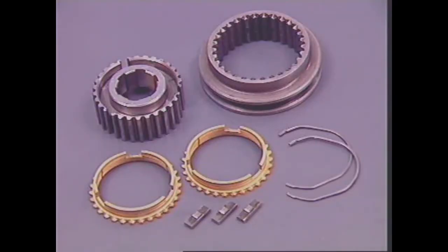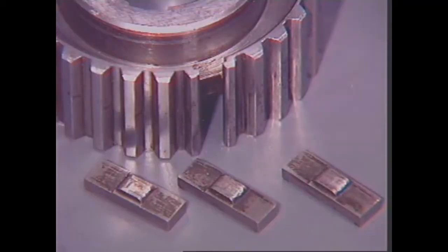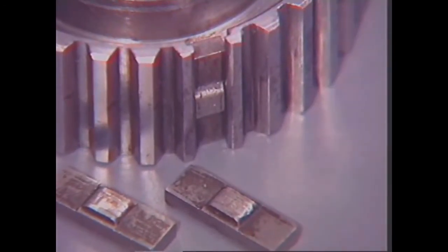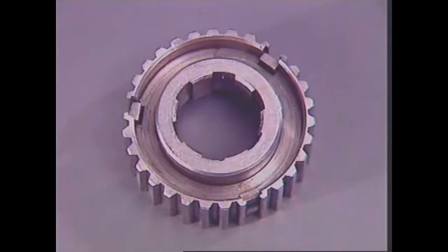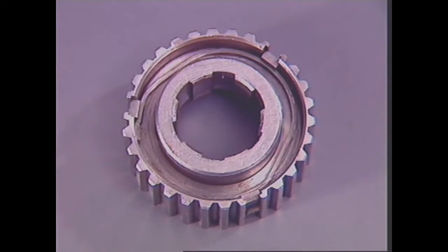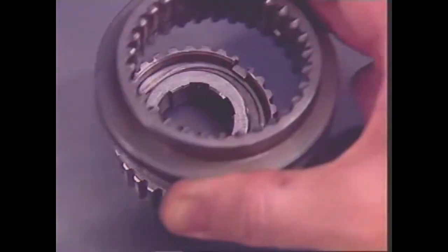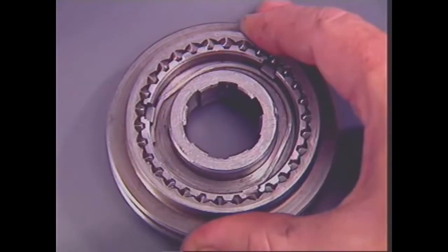A Borg ring type of synchromesh unit is commonly used to synchronize the speeds of 2 gears before engagement. 3 metal inserts with a ridge fit into slots in the hub. A radial spring at each end holds them out, so that the ridges locate in a groove inside the sleeve and hold it centrally on the hub.